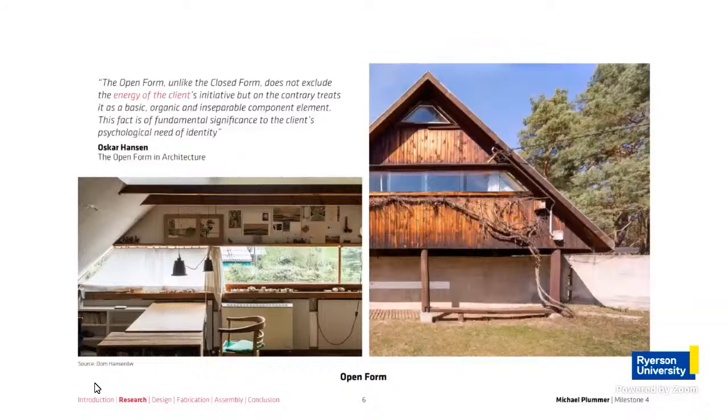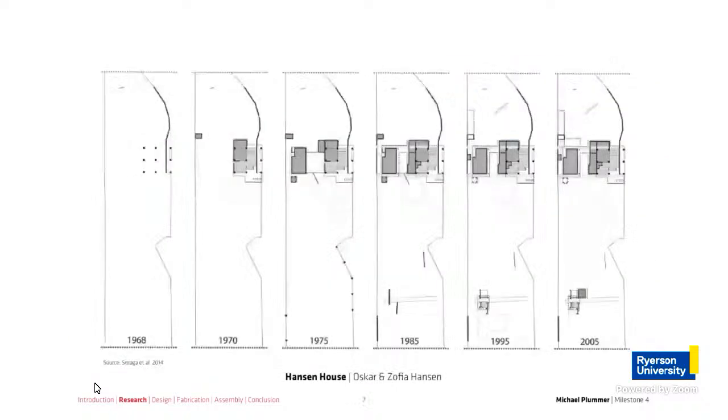The timber-framed pitched roof has no interior load-bearing walls, allowing for endless configuration and reconfiguration of interior spaces. However, the project did make use of building technologies that are more resistive to future change. The reinforced concrete wall is difficult to modify once fully cured. New openings would require specialized concrete cutting machinery and expertise. Something as simple as attaching components to the wall requires special anchors and adhesives.